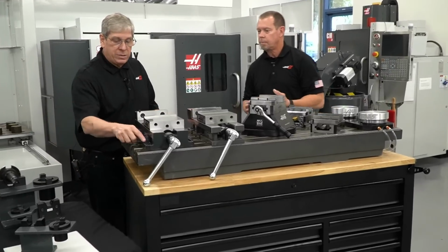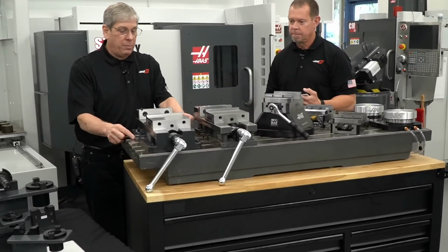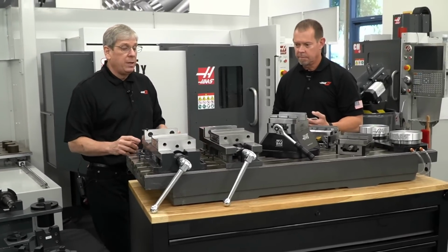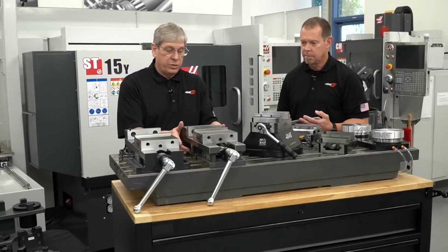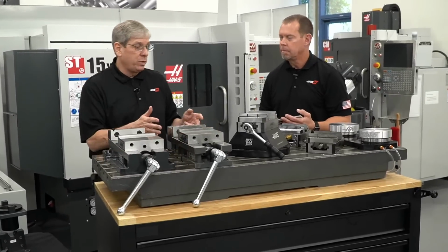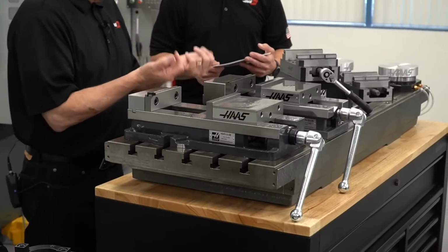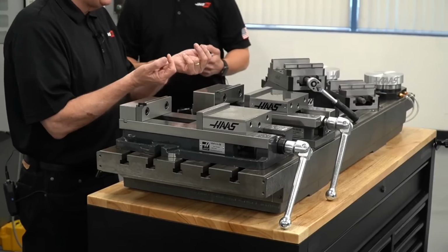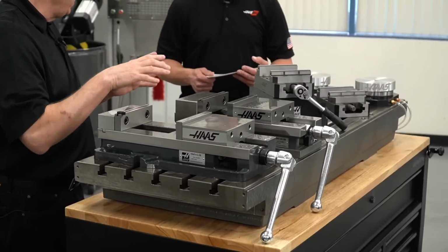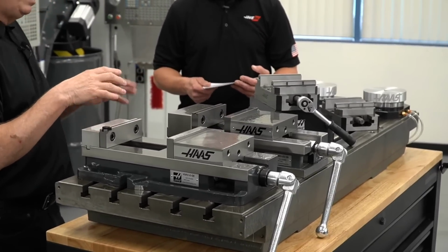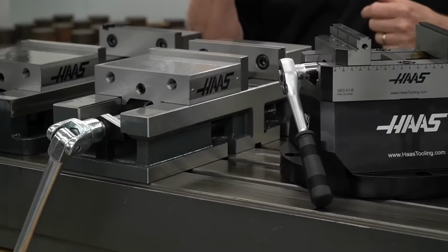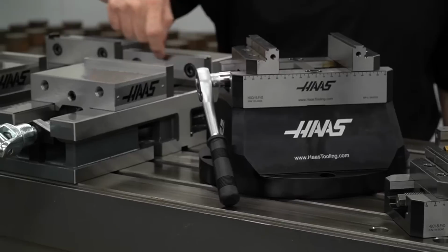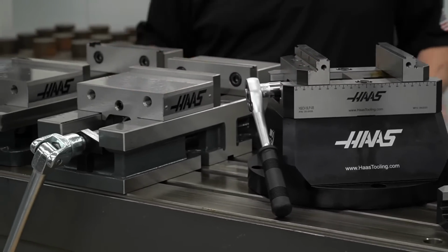We've got the wide base style here that bolts down in 2 places, and you can also put toe clamps on it. And then we have the narrower base with 2 sets of slots that'll line up with the T-slots. They come with keys that you can put on the bottom, and then you drop the keys into the T-slot, and you don't need to square that vise up. I did one the other day on the UMC 1500 Duo, and it was about 6/10 of an inch across the entire 6 inches. Pretty impressive. Yeah, as I set it in there.